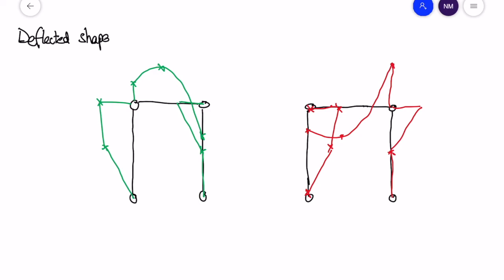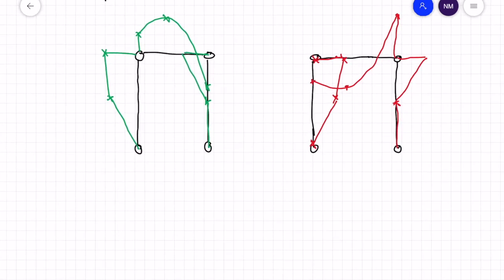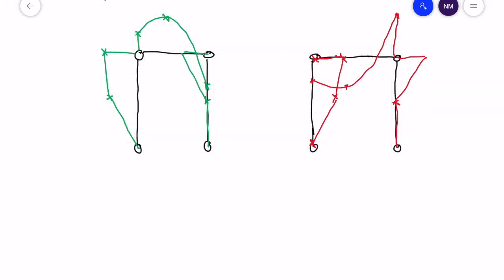Try now to join or connect the 3 inverse bending moment diagrams together, which will give you an indication of the deflected shape of the beam. Again, this is only a sketch, but it gives you an idea of how the structure would actually deflect with the applied loading.